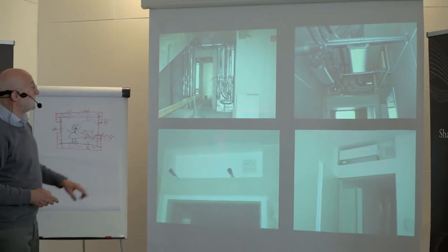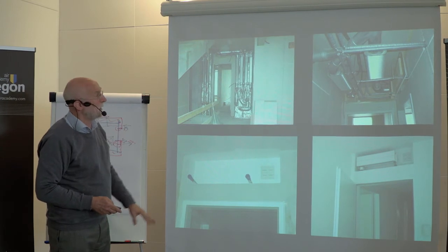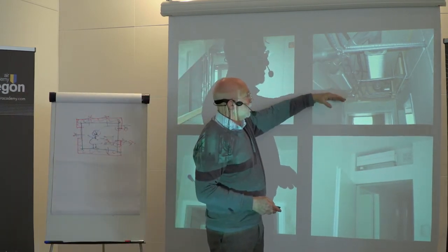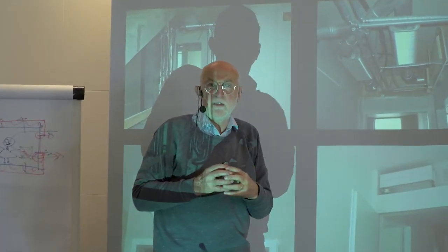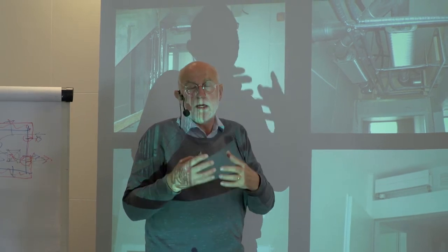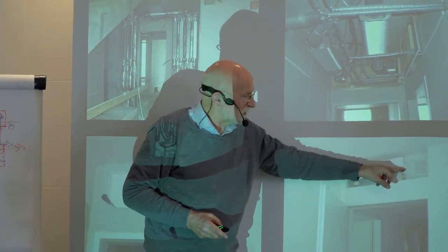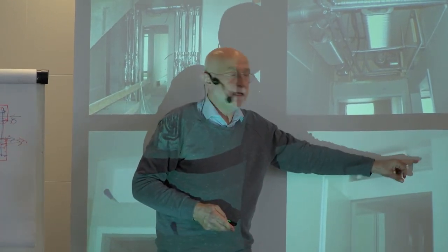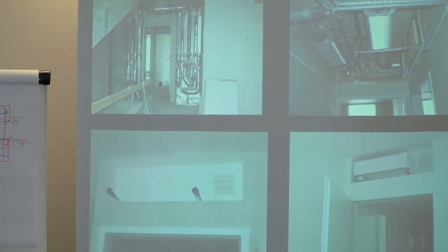It's again the system, the ducts in the stairway, the distribution in a double ceiling, and since we have a passive house with very little energy demand, we can do the heating with this very small heating panel, which is beside the incoming air, and so far we need no more heating panels inside.